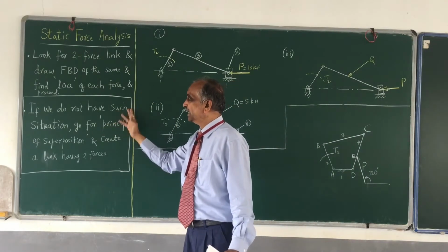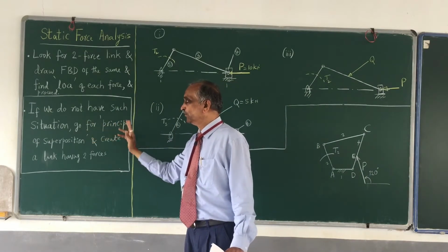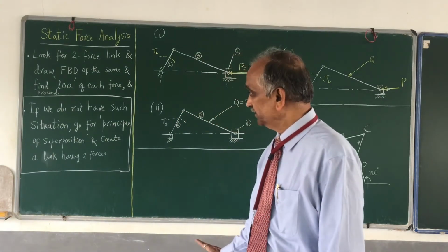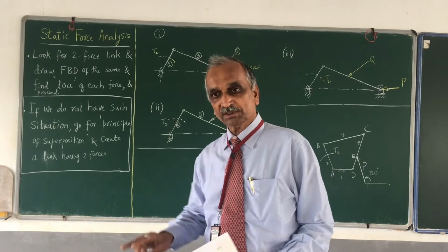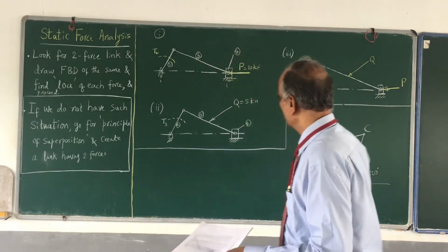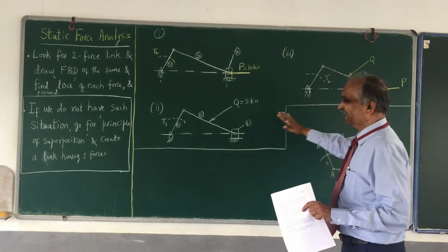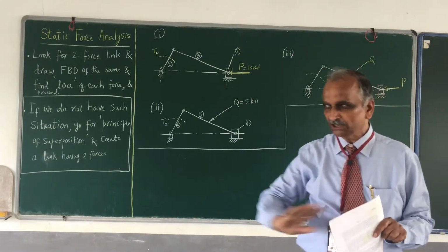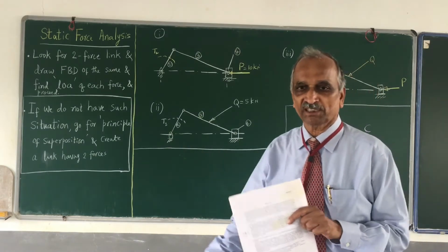If we do not have such a situation, then go for the principle of superposition, create a link having only two forces, and then proceed. This is what I mean by this. This is not applicable only for the slider crank mechanism. This is always applicable for any problem of static force analysis.